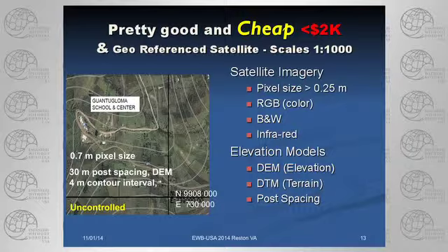You can also get it in infrared, which is a false color, and that color will show wet spots differently than dry spots, so the locations of stream beds or where you might have a possible spring location are more evident if you get infrared photography. In the case of black and white, the nature of black and white is to get a sharper resolution of the different colors. As good as it is, though, you're not going to pick up a grass hut in the middle of a straw field of the same color.